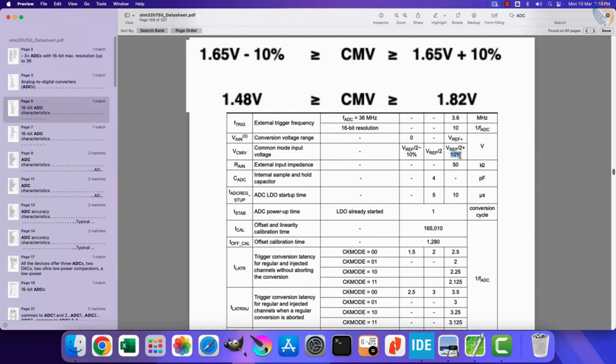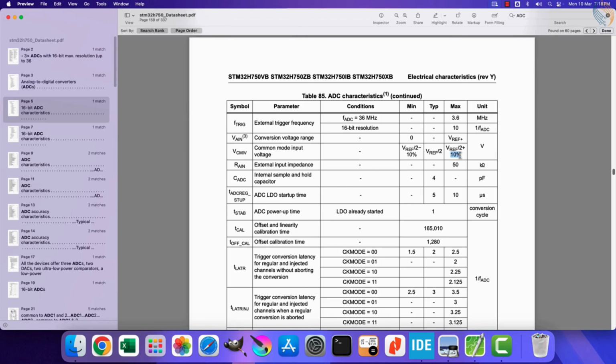When choosing the input voltages on both the differential pairs, make sure the average of both voltages lies within this range. It does not mean that it will not work outside this range, rather the result outside this range is unpredictable. In certain cases it might work, while in other cases it won't. We will also see this in a while.